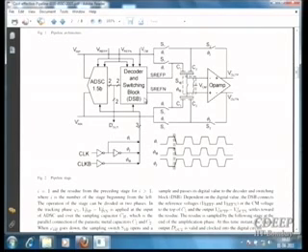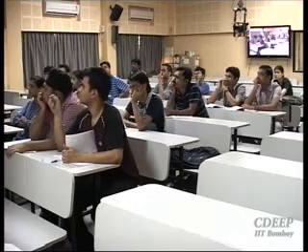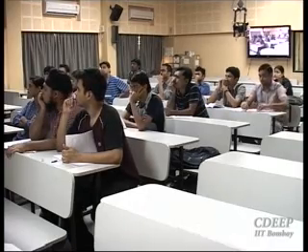So according to the current bit, either it will be 0 or it will be Vref by 2 or it will be minus Vref by 2. Means that either here you will have 0, Ref P or Ref N. Again here you will have 0, Ref P or Ref N. Here they are showing Ref P, Ref N, but actually Ref P and Ref N can have 3 values. These are connected during hold mode.